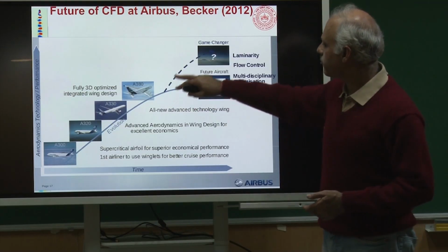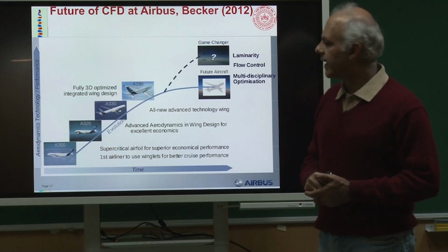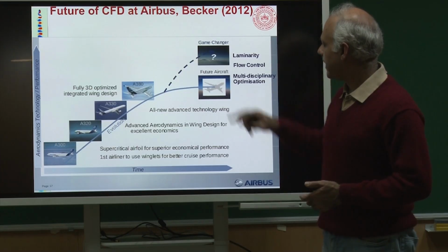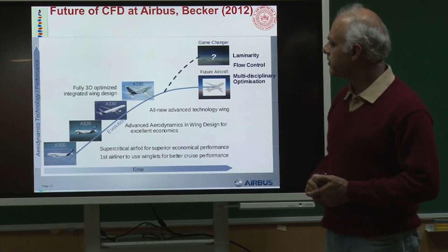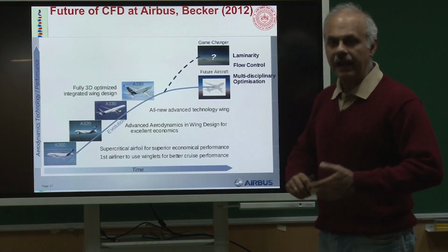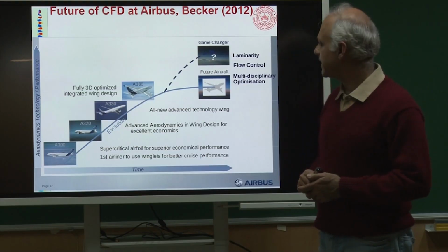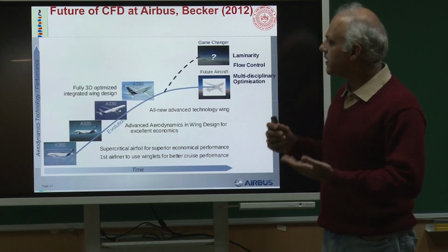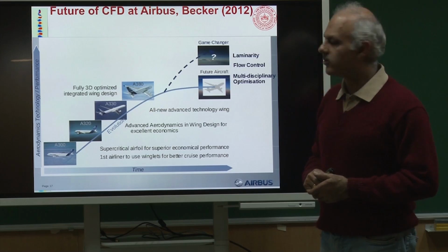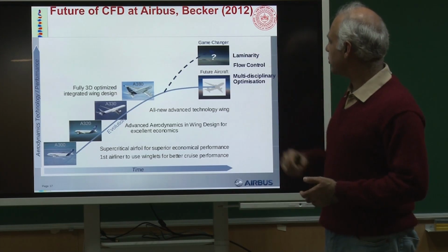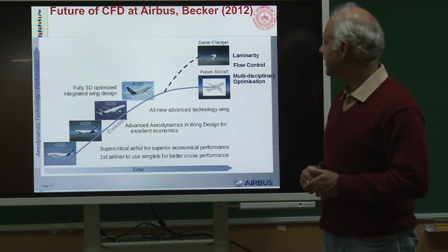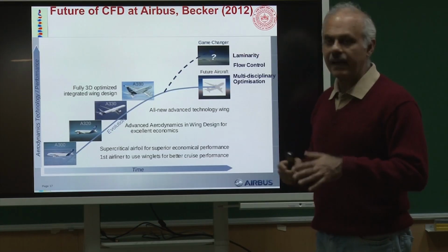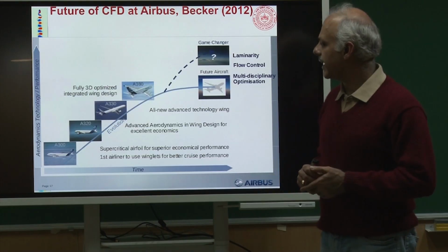But if you want to leapfrog to the next level and get an aircraft which is very high on performance and uses state of the art technology, perhaps something that is only in laboratories these days, then CFD would help you a lot. If you could do flow control and use multidisciplinary optimization, for example, the wings would deflect under the air loads.